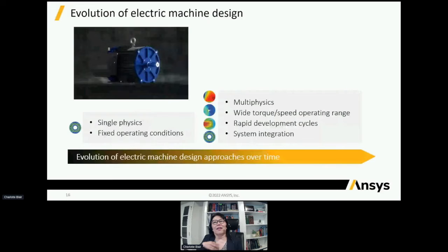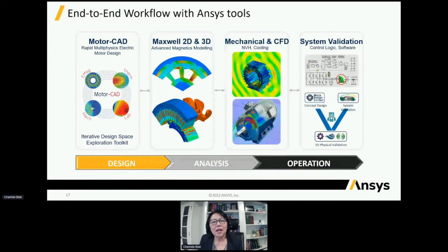So when I say simulations, I mean we're doing that digital twin. We're going to take what I saw as a real component, that blue cylindrical looking thing with those triangular slots in it, and I'm going to create the geometry model of it. And I'll change maybe the number of slots, the number of poles, and the wire, the windings that are inside the motor there.